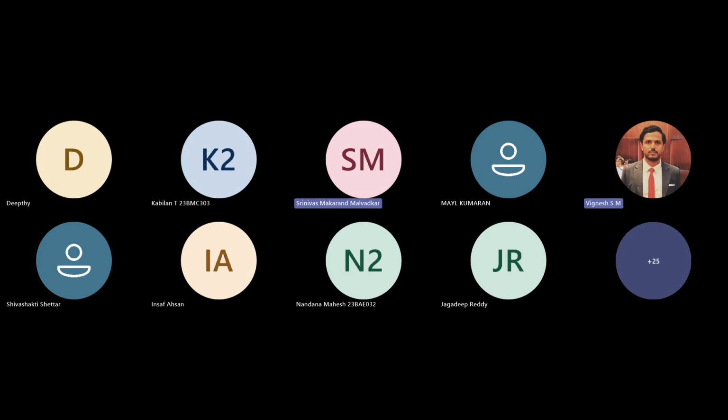So grid independence is to manually converge the solution? Yes, we have to check manually whether, if you increase the mesh size, there is any change in the results or not. If there is no change, you have to stop just one step behind that. Okay, sir. Thank you.